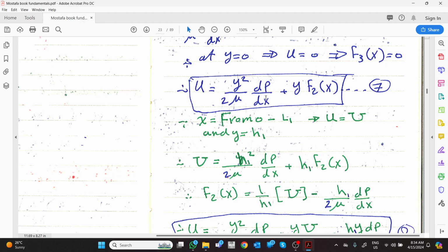When we have a derivative term, we know that this is changing in the x direction due to the change of the area, not due to the pressure. If it were due to the pressure only, we could use the approximation, the pressure at the start and the pressure at the end divided by the length, to get this number. But the pressure is changing because of the change of cross section.